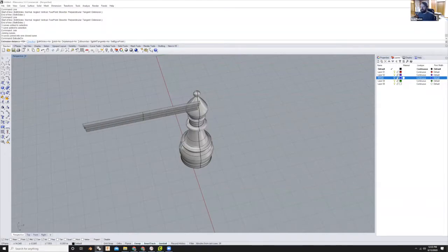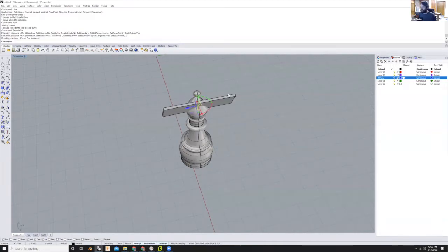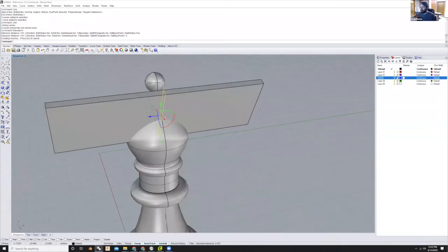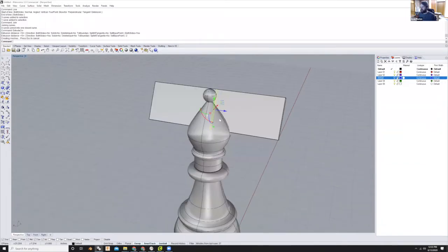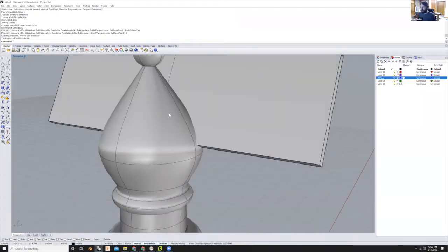There are many different options here. You can change the direction, you can change both sides, solid, and so forth. I'm only going to stick with these first 2 options here. So I'm going to click on both sides, and now it's going both ways in the distance that I specify. So I could type 2, and it's going to go 2 inches on either side of that curve.